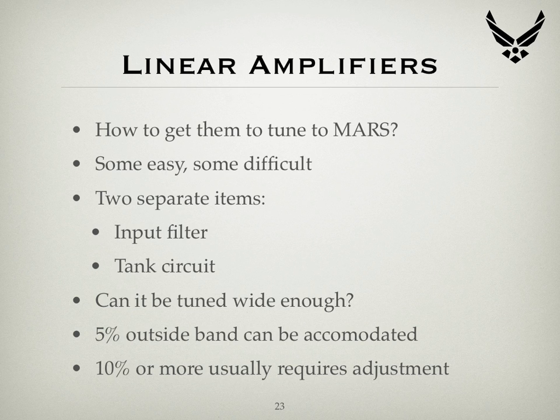Now two separate items really need to be looked at. One is the input filter itself, that is the input filter that does the impedance matching between the transceiver and the valve or transistor stages within the amplifier, and also does some filtering to basically prevent harmonics from being taken into the main amplification circuit and being amplified and sent out. Now if the input filter can't be tuned, you've got to look at it and say, well, can you tune it to an appropriate range to allow for the M.A.R.S frequencies.